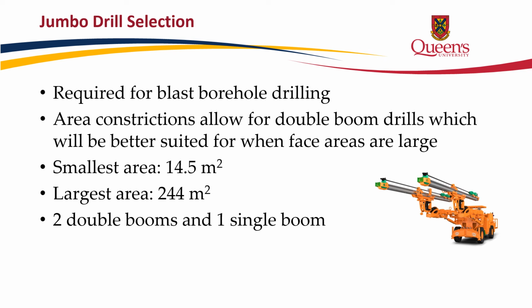Because the large working face is 244 meters, 2 double boom drill jumbos and a single boom drill jumbo will be used. The single boom jumbo will be especially valuable when varying thickness and working face becomes very small. When it is not required, the small drill jumbo can be used for rock bolting purposes.